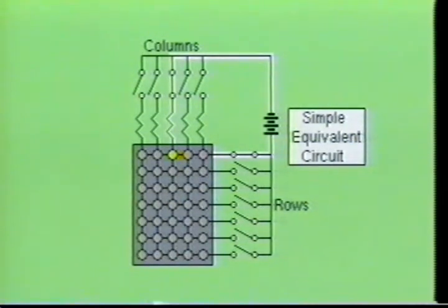When the character generator scans the first row, the LED in column 3 will be high. Therefore, the LED in column 3, row 1, will be energized. Next, the character generator will scan row 2. As row 2 is being scanned, inputs on column 2 and column 4 will be brought high. This allows the LEDs in column 2 and 4, row 2, to become energized.